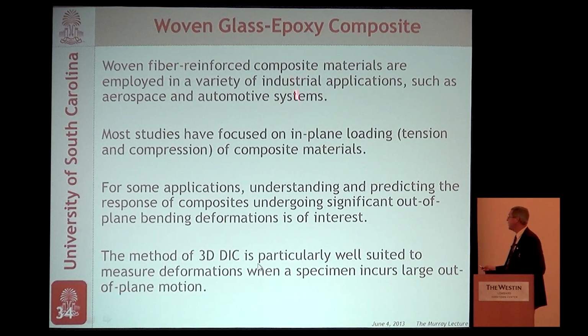This briefly says the same thing I just talked about. It turns out that the 3D DIC method is particularly well suited for this, because as you bend it and compress it, the deformations become extremely large. And yet the specimen survives. It is damaged, and the question is, what can we tell about what happened to the specimen?